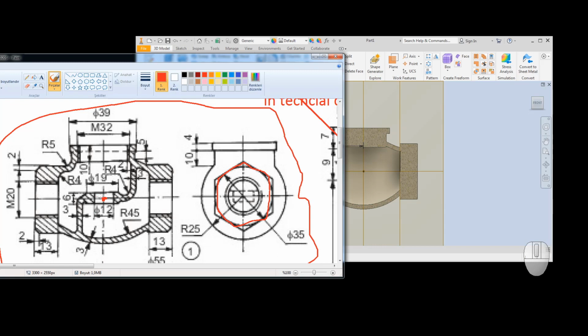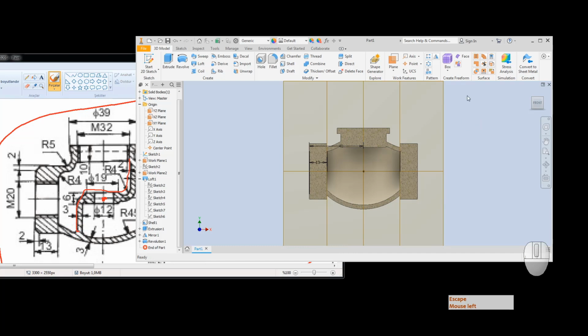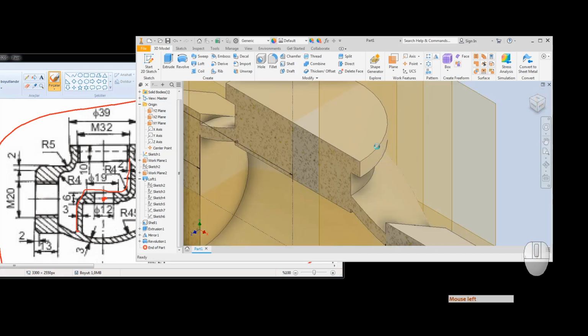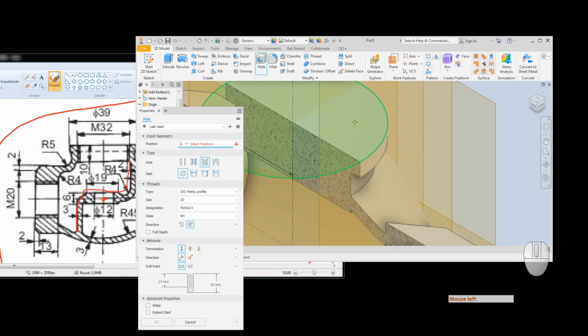At this point, we are going to start the hole creations. After the hole creation, we are going to add the inside body features. We start the hole feature by selecting a surface and moving the hole point and stick that point to the hole here. We have on the top side a threaded feature here, and we will just move our point up to this point.